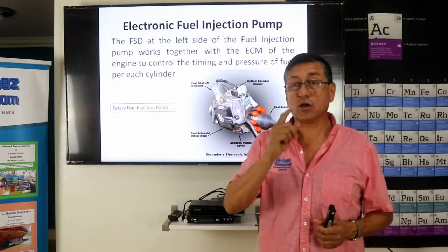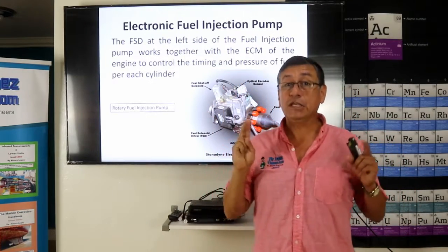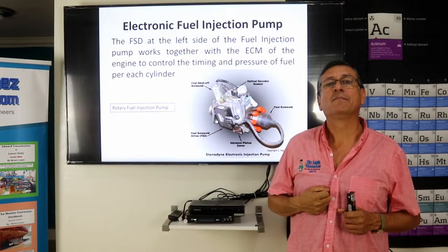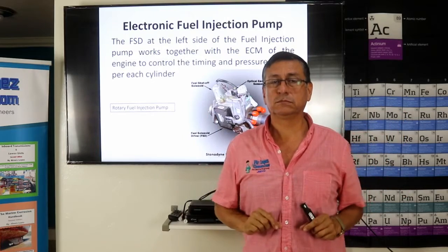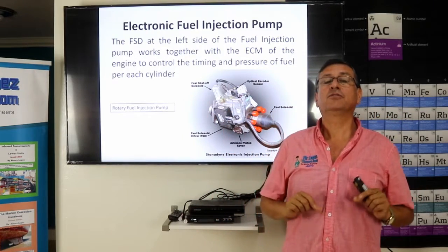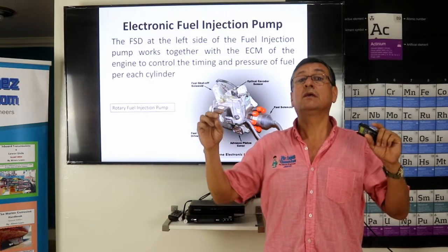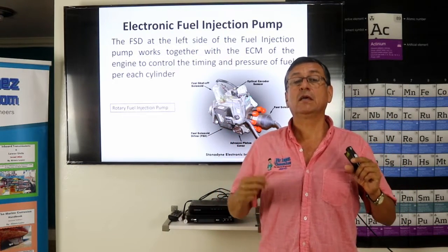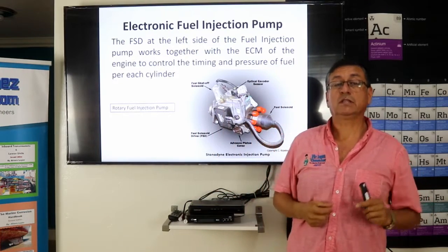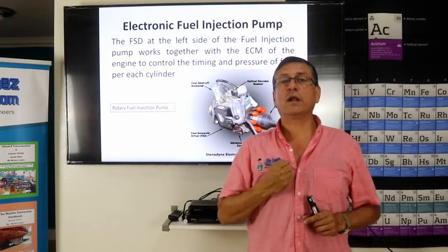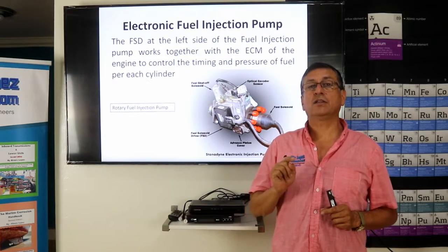How many returns do I have in a typical diesel engine high pressure common rail system? I have one return on the fuel injection pump. I have another return on the injectors. And I have another return on the manifold. The high pressure supply manifold has one return. If the pressure is superior to the limit recommended, the regulator returns the fuel into the tank. I have three returns: one on the injectors, one on the rail, and one on the pump.